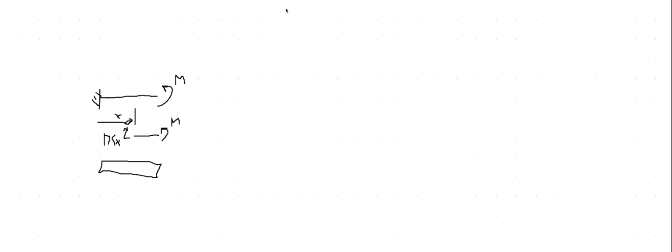So here's what I'm actually studying. For example, I can take a cantilever beam and apply a bending moment at the end. If I take any point x, with the beam going from 0 to L, I take this piece of the beam on the left-hand side and the right-hand side. I should be applying the moment which I equilibrated. From this I conclude very quickly that the bending moment diagram should be constant: M of x is equal to m, a constant.